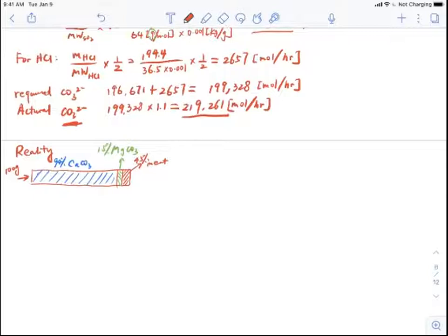So I didn't quite understand your question. You can unmute yourself. Yeah, so you have 4.5% something, but I can't read what the something is. Oh, the 4.5 is inert. Inert, okay. Yeah, that's the inert. So basically in the limestone, you have something that's not reacting with the acidic gas at all, right? You don't have a stone that is made of pure substance in there.